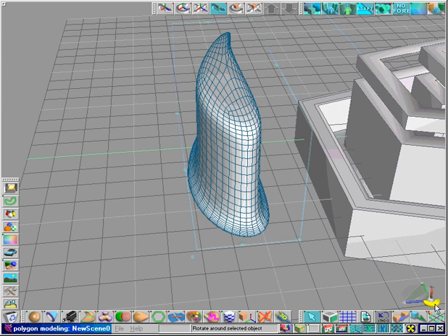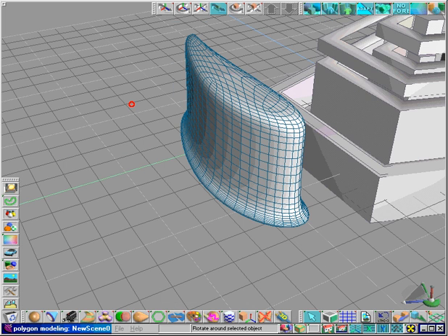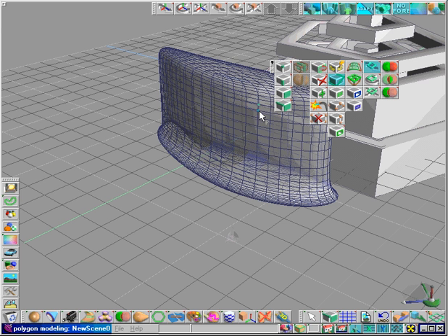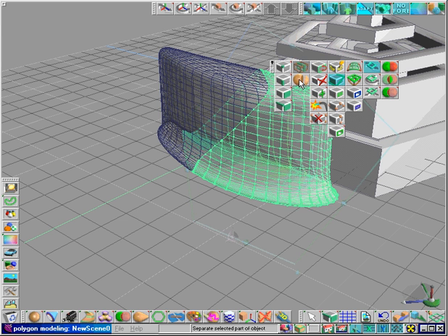We can use the Polygon Slice tool to create any cutting plane we desire. We do not have to follow predefined edges. By selecting a starting and ending position, we create the hinge line for our slice. The third point defines the angle of rotation around that hinge. If you are cutting across any holes or gaps, remember to hold down the Control key. We have now created a slice plane of new edges. A fourth selection will highlight which side of the slice plane we want to pick. The Separate tool will split it off.